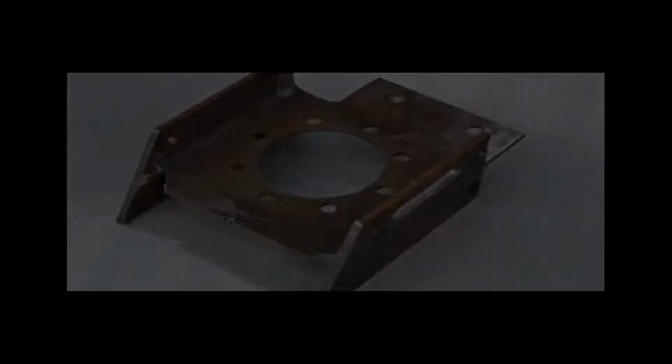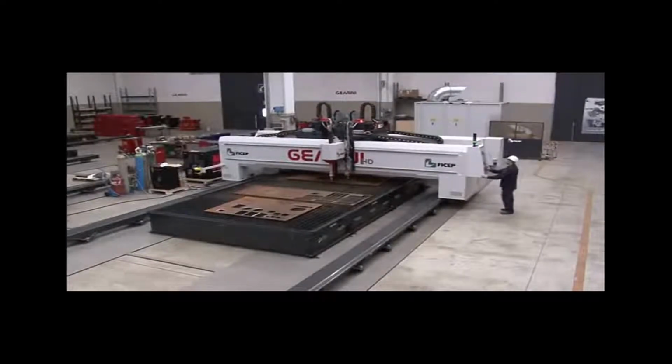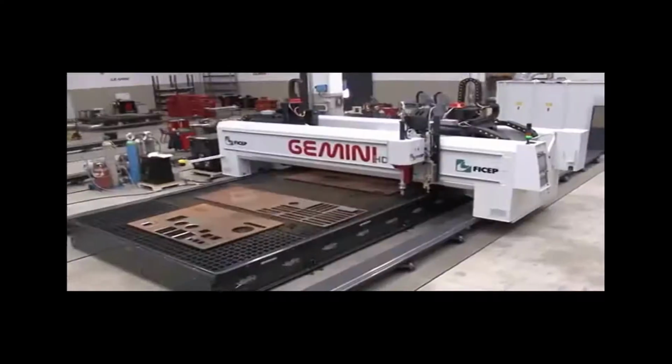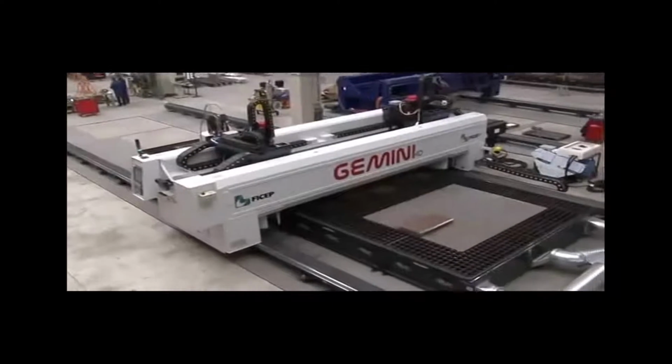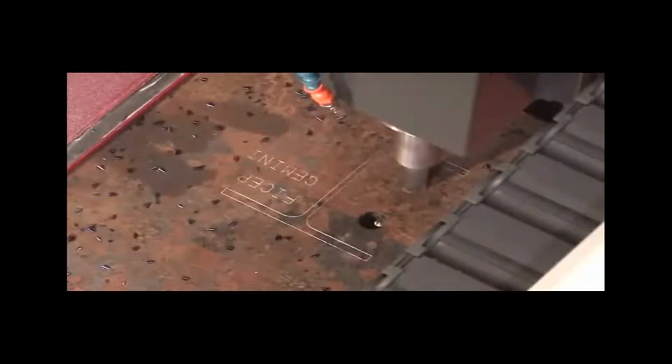Okay, so we've taken a look at linear elements to the machines, and again the final one now is of course the plates. So with the plate nesting, the information is passed directly down to the machine, in this case the Ficep Gemini. Just an example of how the machine looks. You can see the nested parts onto the plates there, but again the information of that nesting is passed through to the machine. Again, this can also do the layout marking, information on cutting, even including three-dimensional preparations can be done using this machine as well. Again, all passed through from the Tekla model.